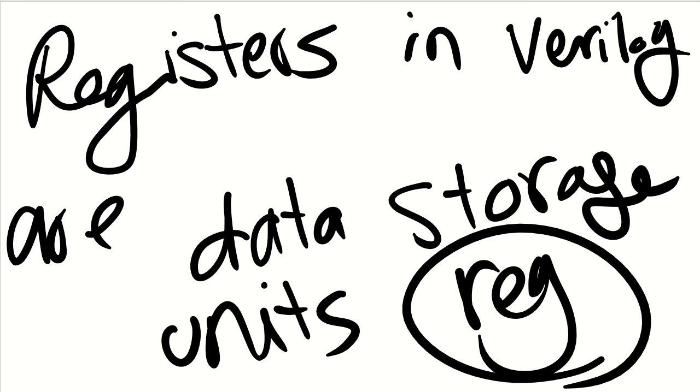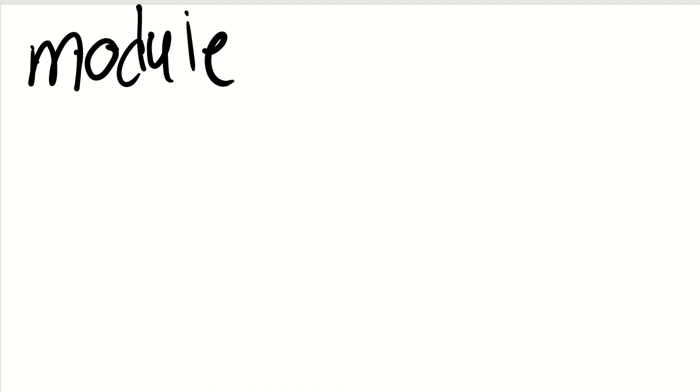So if I want to write a code for this, I'm going to say, okay, first I have to use the 4-bit adder. I'm going to use the keyword module. You know that by now. Then you know that after module, I have to put a name for my module, which should make sense. I mean, Verilog doesn't care, but for you, usually when you write a code, the name should make sense. So let's call it 4-bit adder.